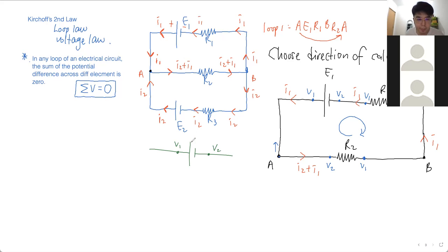The positive plate is always higher potential, remember, okay? Because current flows from high potential to low potential, just like water flows from high pressure to low pressure. The positive plate is high potential, the negative plate is low potential. So we take V1 minus V2. After you distribute this, V1, V2, we always take V1 minus V2. We always take point number 1 minus point number 2.